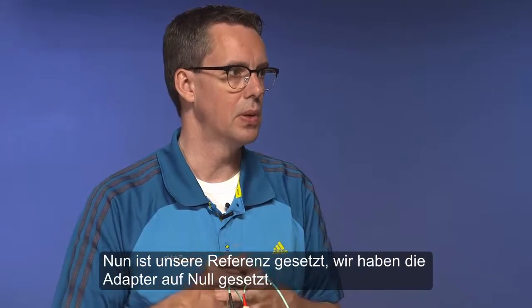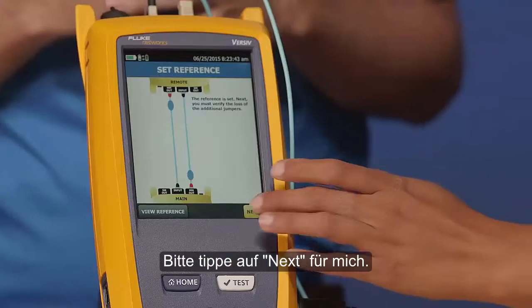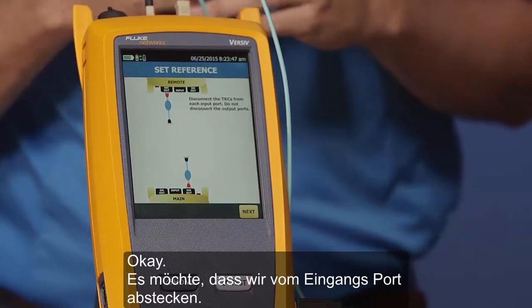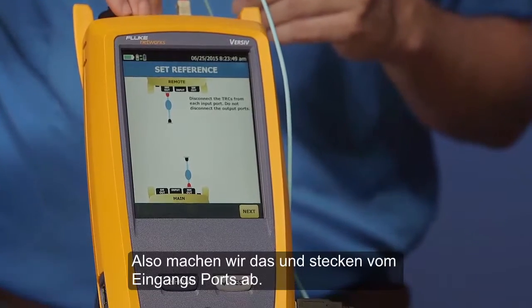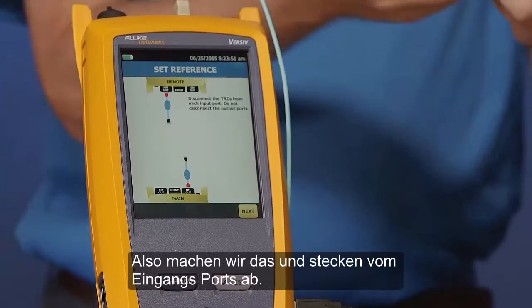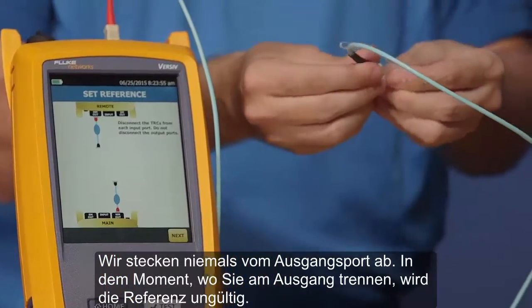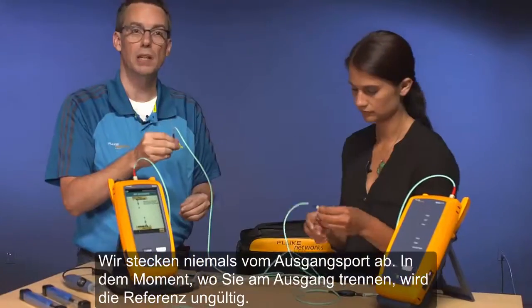We've zeroed out these cords here. Go ahead and tap next for me. Okay, it wants us to disconnect from the input ports. Let's go ahead and disconnect from the input ports. We never ever disconnect from the output ports. The moment you disconnect from the output port, that invalidates the reference.